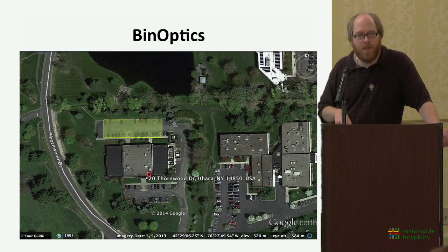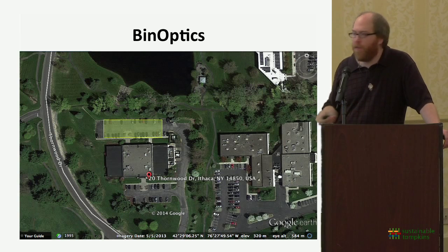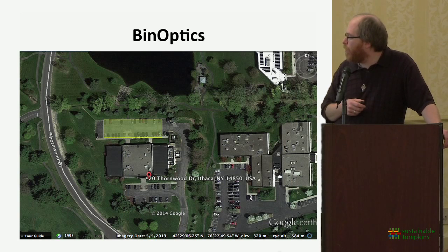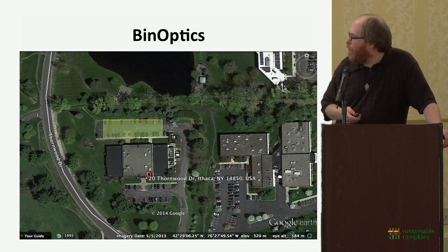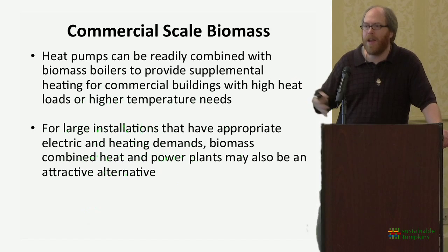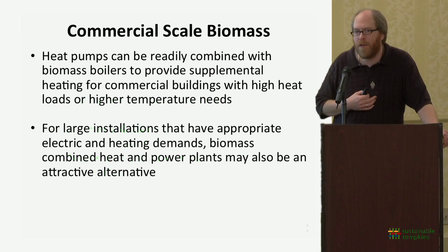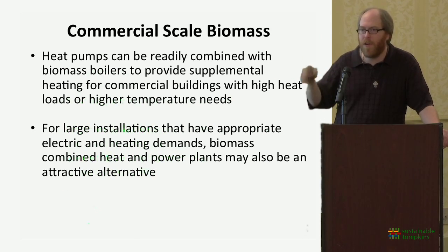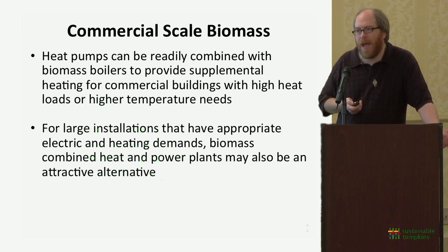And just like we found with Village Solars, the parking lots are generally always going to be big enough for you to fit the well field. The well field to heat Binoptics, if you went just with space heating with ground source heat pumps, would fit comfortably under one of their two parking lots. When you need higher heat loads, when you need process heat, heat pumps are great up to 110 degrees. If you need heat that's much hotter than that for steam, if you need much, much higher heat loads or heat loads that are spiked during very narrow times of the year, you can then begin to look at biomass.